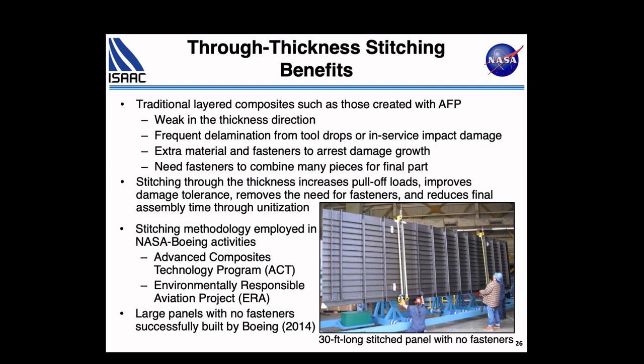With composites, it is possible to have significant damage and not be able to visually see it. Aluminum, you get a dent, you know it's there. Composites aren't that friendly, which is why you have to be really careful and understand the different damage scenarios and damage mechanisms and the consequences of that damage, compared to the simpler case of looking at aluminum.